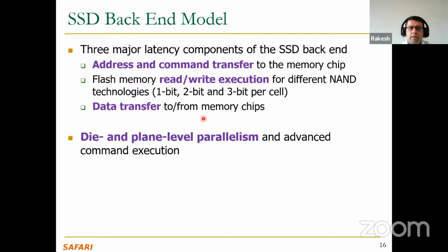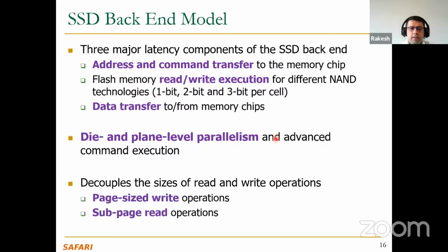the controller. MQSim also has implemented die and plane level parallelism, which means that the commands can be sent to multiple dies, and it also supports multi-plane operation. And MQSim also supports advanced command execution. One such command is multi-plane operation, and there are other commands like copy back operation as well. Then MQSim also decouples the size of read and write operations.